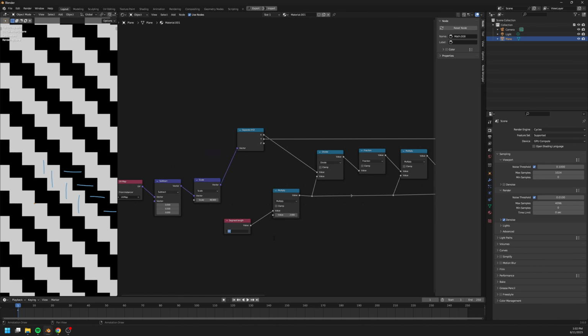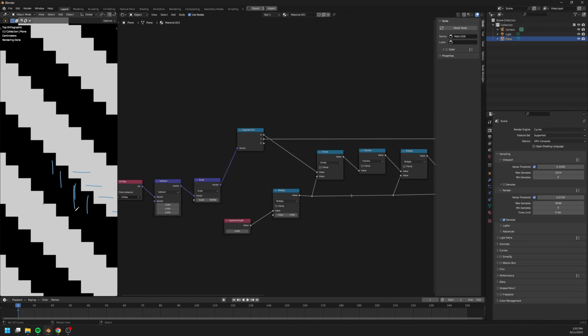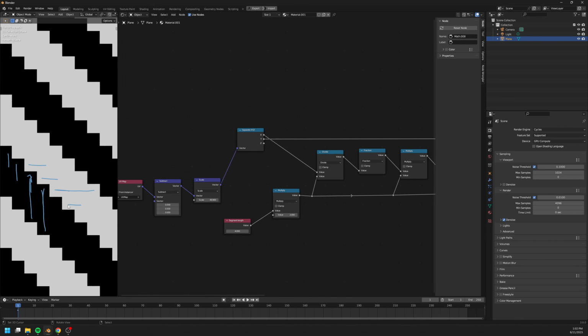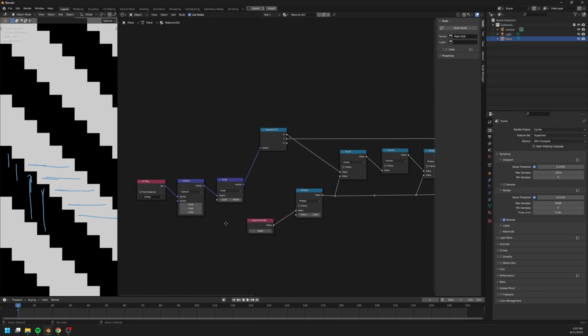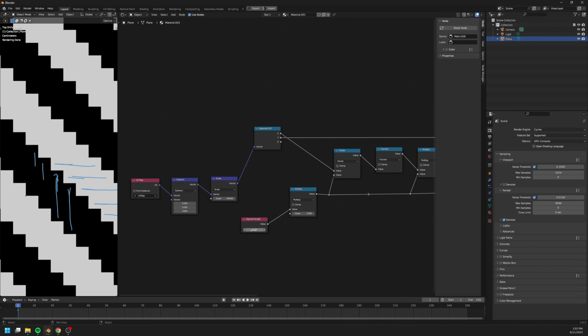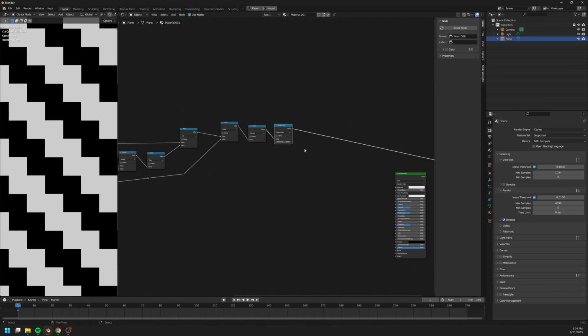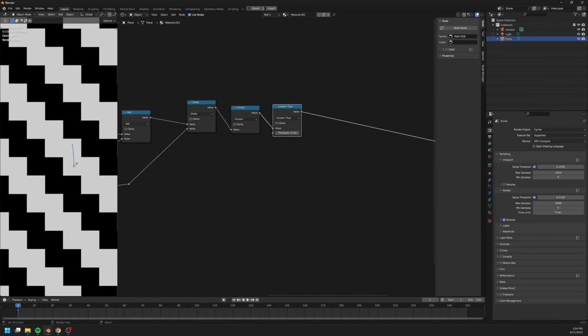And if we set this to, let's say, 4, then the segment length will be 4 units, like so. And likewise, the horizontal segments will also be 4 units, like so. But usually for carbon fiber, we will use 2, like so. At this point, we have the mask for the alternating carbon fiber directions, alright?